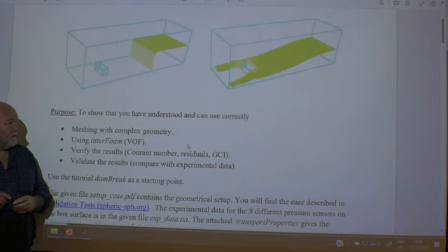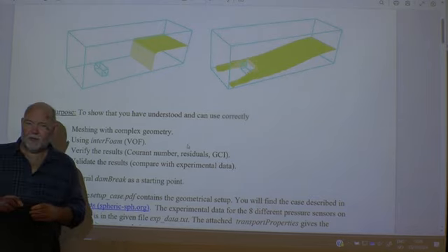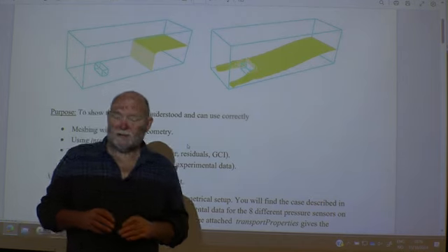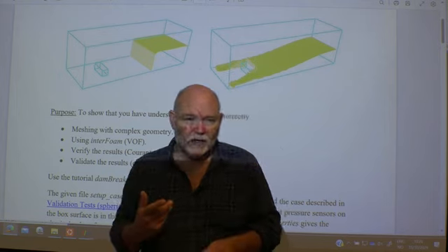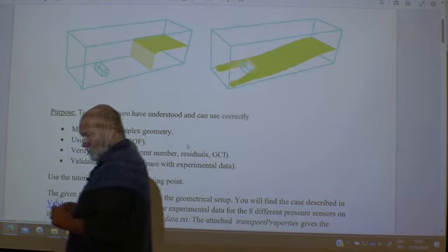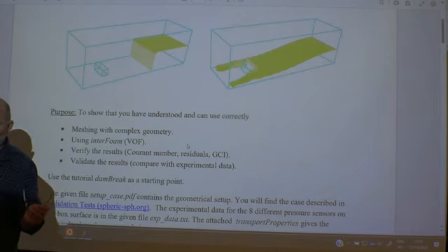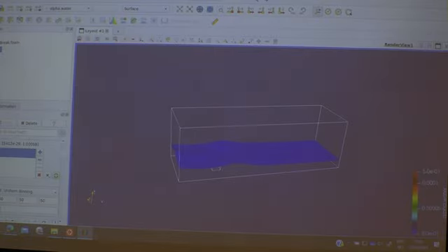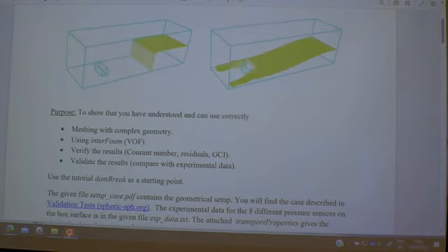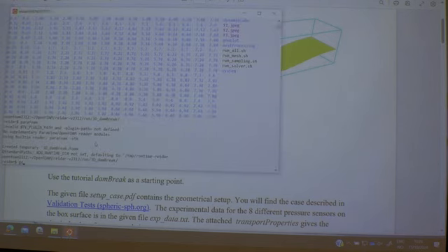That should work. Or you can use snappyHexMesh but not use an STL file, an object. You can create simple geometries inside snappyHexMesh without an STL file. That's actually a possibility. Let me show you. Where are we? Here. Gedit, system, snappy.